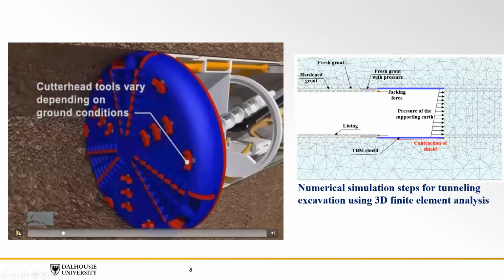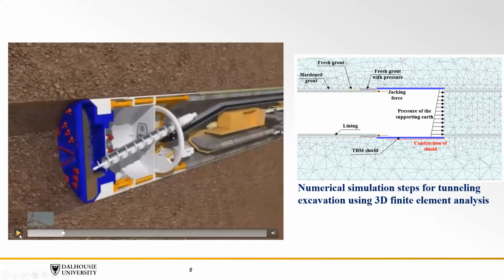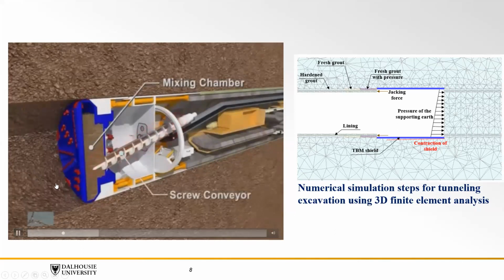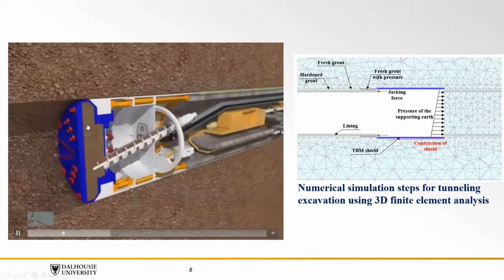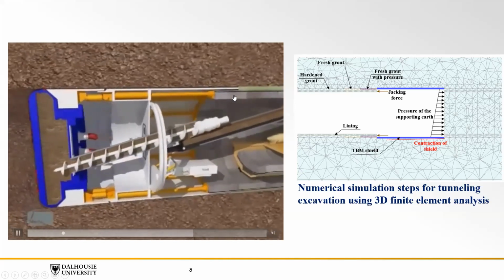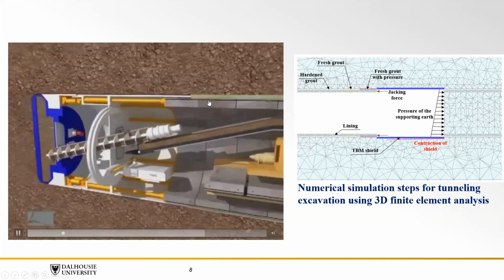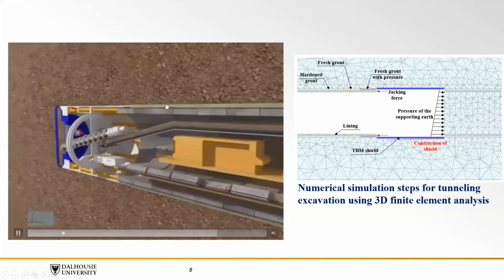What did earth pressure tunneling involve? If we look here, this is a tunneling machine. It is a slightly conical shape, and we have the face pressure here. As it excavates, the products of the excavation are conveyed by the conveyor outside. As it excavates and moves in, we create a void space to install the new segmental lining. And then after we put each segment along the ring, we start injecting grout.